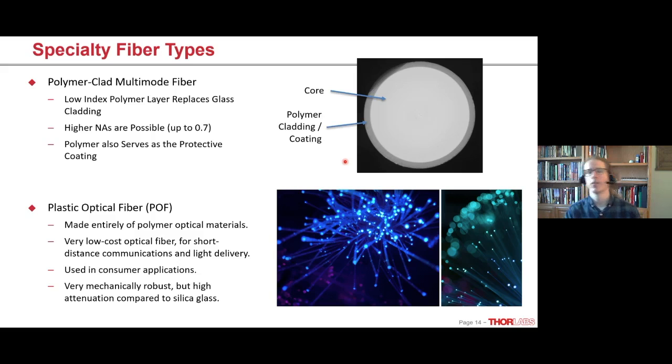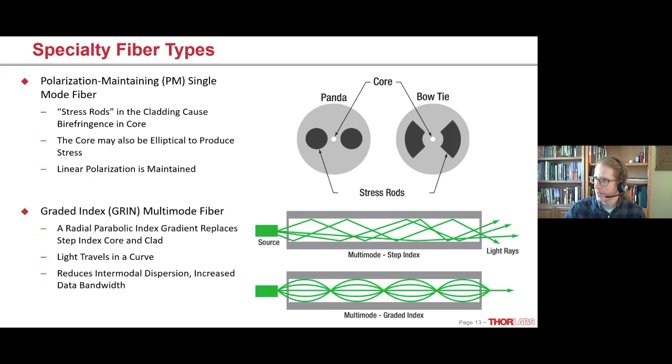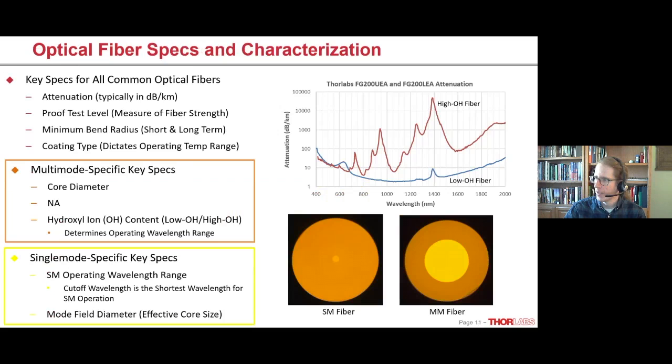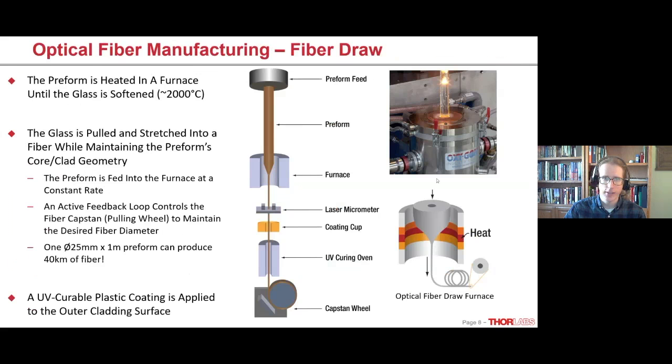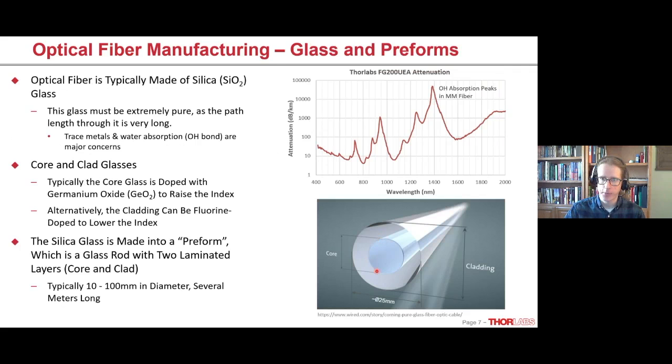All the way on the other end is the nuts and bolts of a fiber draw tower. How do we actually do this process and get it to work right, and get great diameter control on the fiber? How do we make the preform even, and have this core-clad interface be really pure, and therefore support really good total internal reflection and really low attenuation?